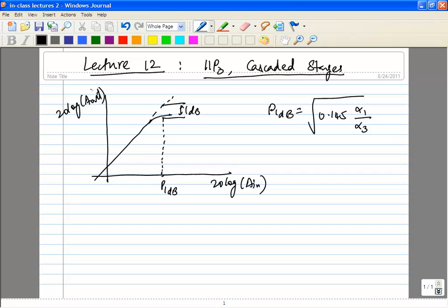No, there is no specific physical meaning, it's just a convenient point to choose. You just need something common to describe across many different kinds of circuits. So this is probably very useful for amplifiers. However, if you're talking about maybe mixers or some other kind of circuits, this may or may not be super significant. It will be, but you may gain more knowledge from the IIP3, right?